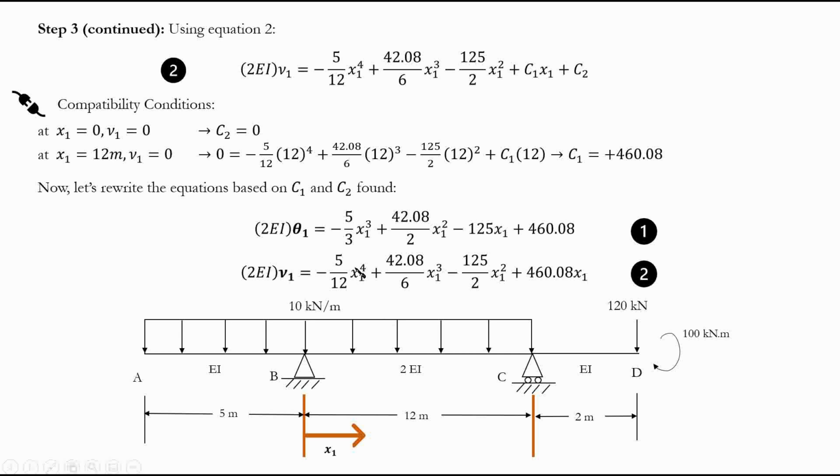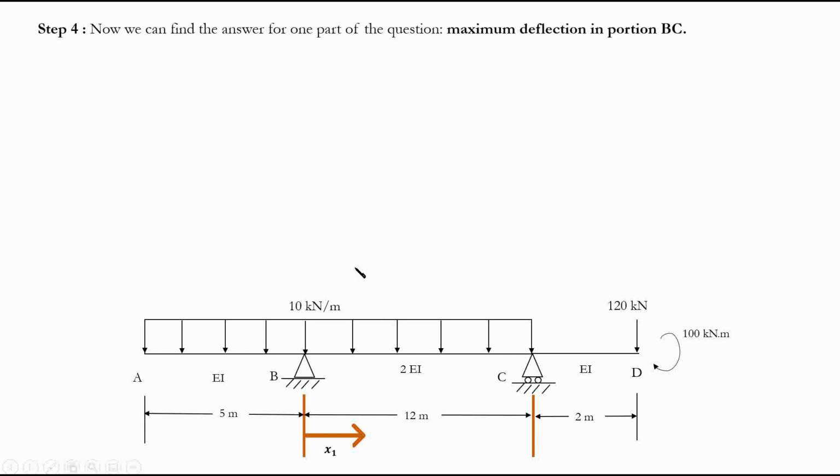So when is the deflection maximum? From calculus, we know that the deflection is maximum when my rotation is 0, when my slope is 0. That's finding local optima. It is not completely necessary for you to find the elastic curve when you're using the method of integration, and sometimes it can be tricky.